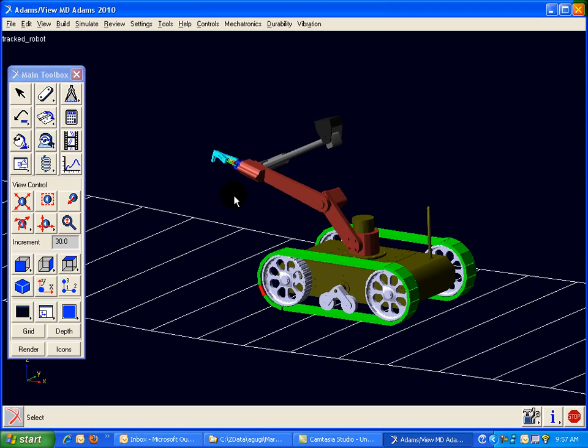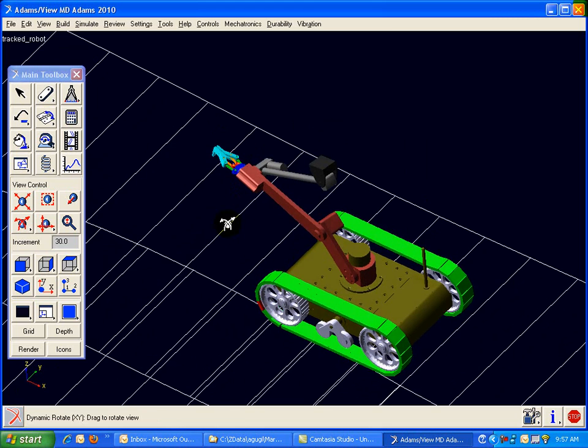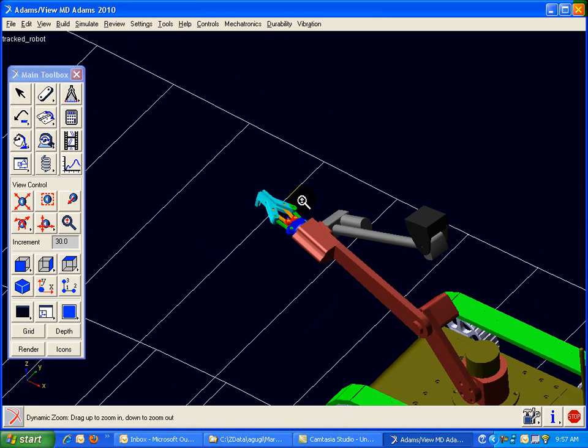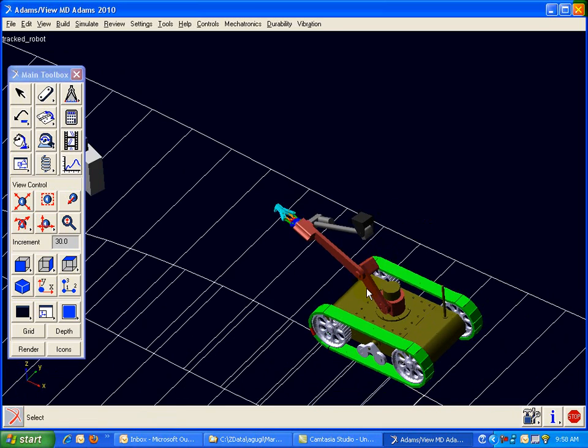On the leading end of the robot here, we have a gripper claw. It's basically two 4-bar linkage mechanisms, and then the wrist will also rotate the whole mechanism about one axis. It's watched via a camera that's mounted here, so that camera can keep an eye on what the gripper is going after.